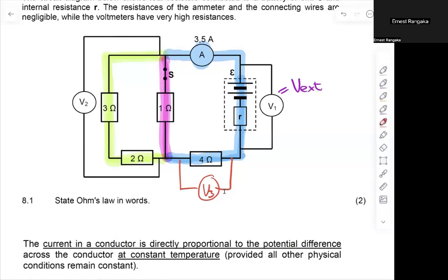Someone says there, on the 5 resistance, total current doesn't go through. I don't see where there's a resistor with 5 ohms. Maybe I'm not quite understanding your question. If you can maybe rephrase it, I'll try and reanalyze it. But I don't see another resistor with 5 ohms, unless you're talking about the 3 plus the 2 as the 5 ohms, but you still have current going through there because my switches are all closed.